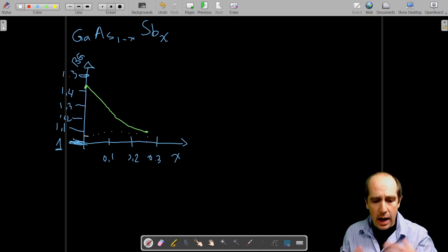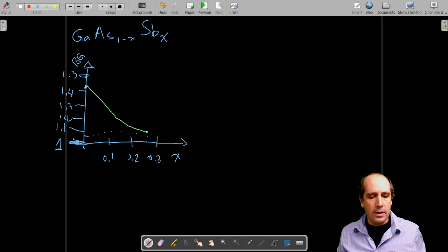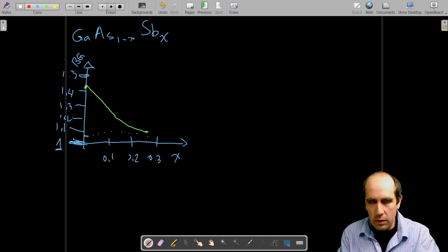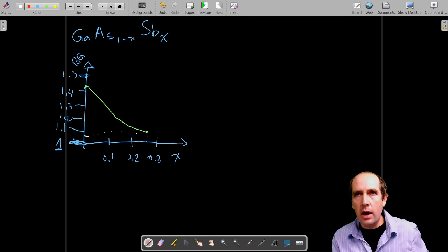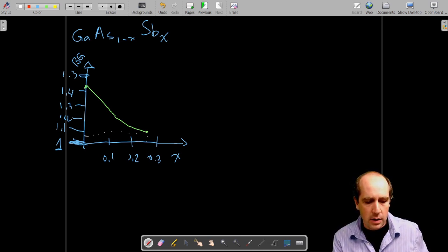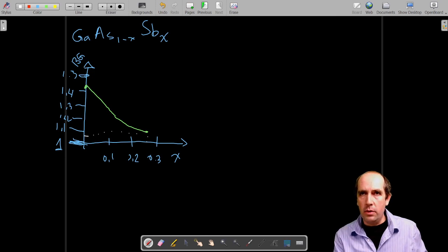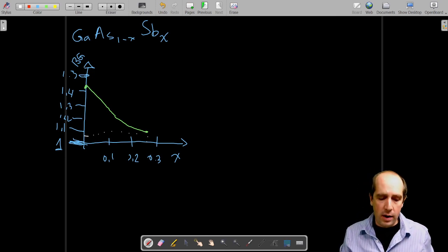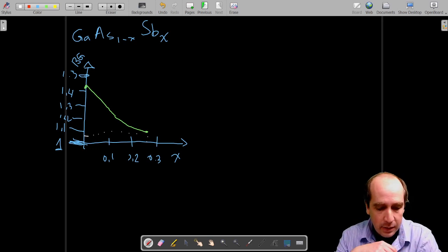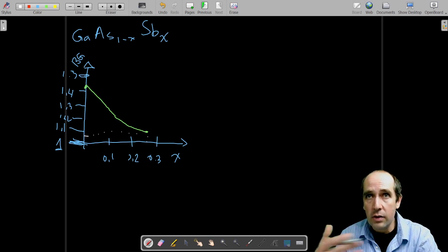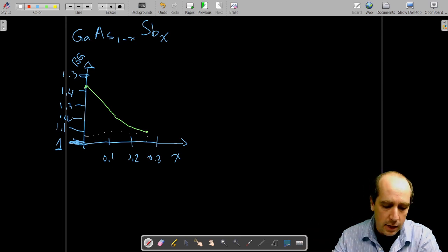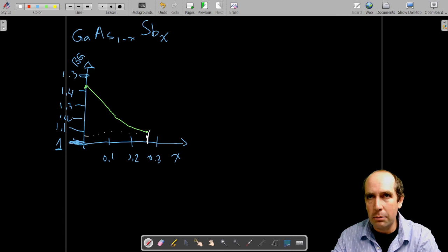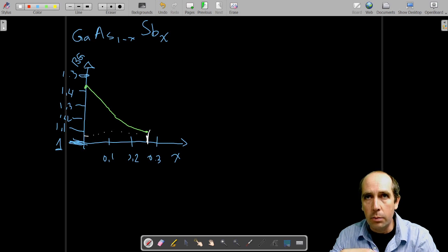So once again, this allows us to go towards the infrared, so we can now tune the wavelength down to somewhere below 900 nanometers, so really well in the infrared, and going towards the telecommunication band at 1.5 microns wavelength. Okay, so again, this is just a series of semiconductors, alloys, and again, at this point here, it stops being a direct bandgap semiconductor, so we're not interested in it anymore, at least not for its optical emission properties.